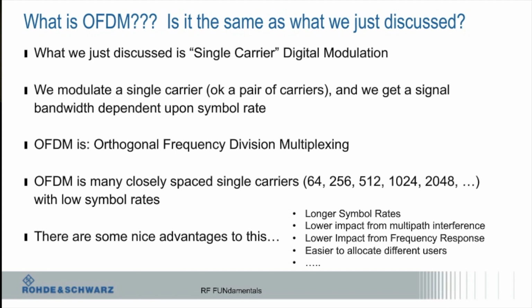The other thing with this is if I have lots of carriers and maybe a lower data rate or lower symbol rate in each one, I can have slower signals, right? So I'm more apt to not get errors. I'm not going to get multipath errors, things like that. If you remember going way back, when I'm moving around, the signal levels are changing very rapidly, obviously because my environment is changing rapidly, the reflections and whatnot. If my signals are coming out more slowly, I care less about that variation, right?